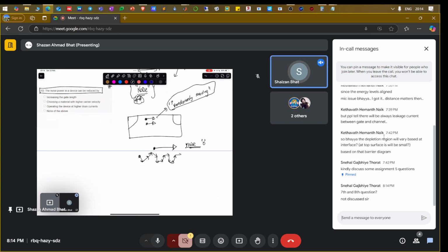Just try to understand what I'm telling. When the electron is moving like this in the channel, when you measure the current or any property, you average it. You average all the values around a particular value, so all these momentum relaxation events, everything, are actually acting as noise. If you could somehow eliminate all those scattering events and other things, you would eliminate most of the noise.